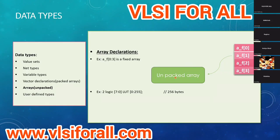So here is a combination of both packed and unpacked arrays. I have declared a LUT which is 8 bits wide, and it has 256 elements. You can consider this as a memory of 256 bytes. Now if I access this with LUT[0], I'll be accessing 8 bits at a time, so basically 1 byte at a time. This is how memories are usually replicated in SystemVerilog or similar languages.